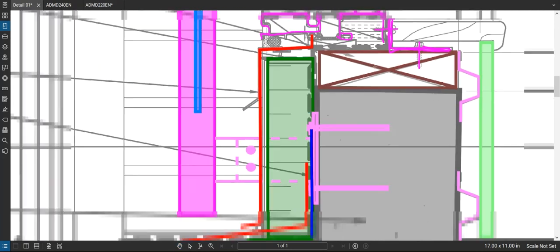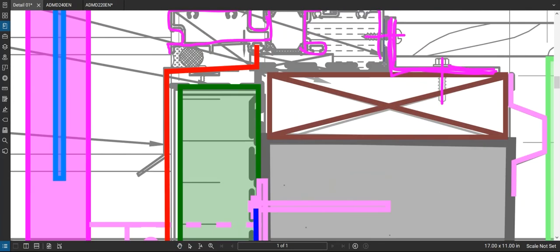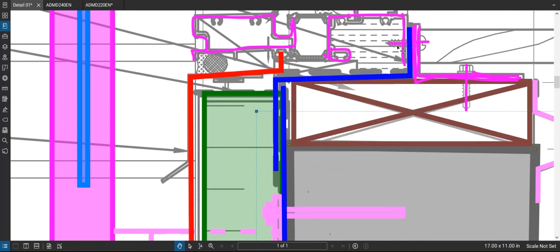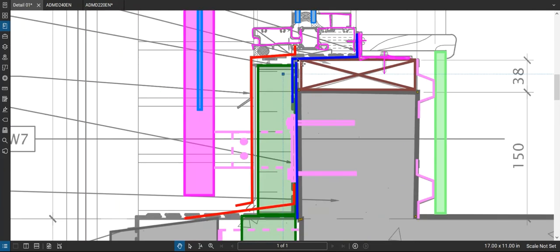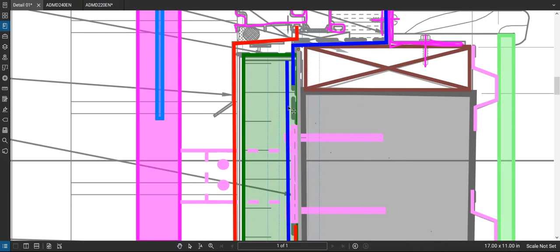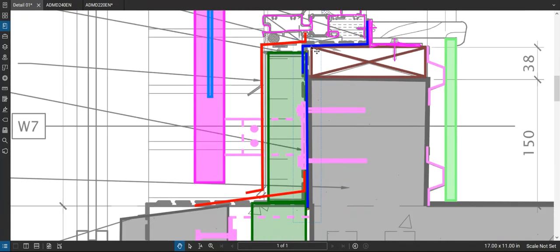And I've mentioned before that we're going to have, actually, let me change my line type here. Okay, so there would be a starter strip put in for the back dam there and on the door sill there, and it would overhang another layer here. So always do positive overlaps, okay? You never want the next membrane to be on that side of the membrane or water can get down into there. So always show them overlapping in a positive way.